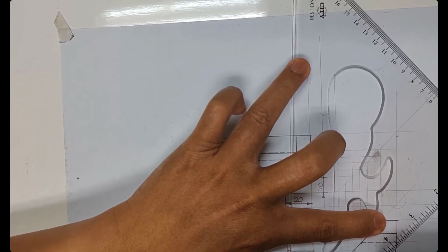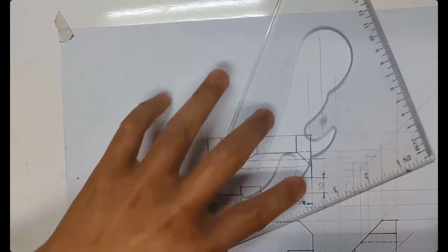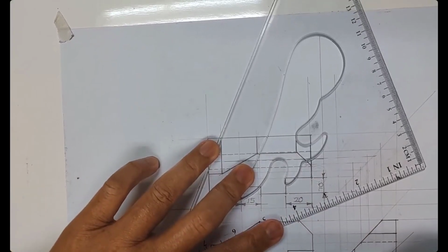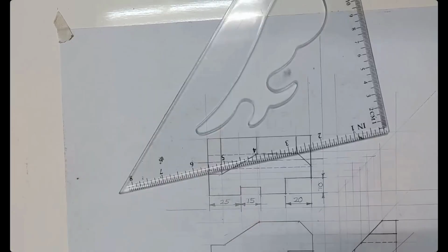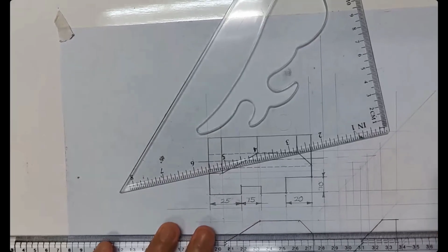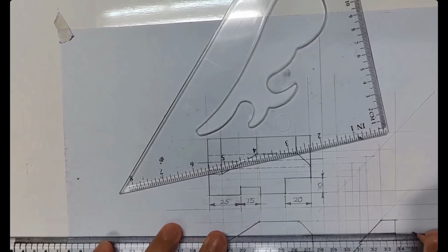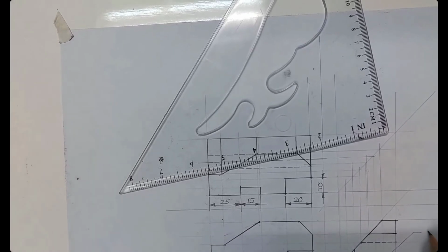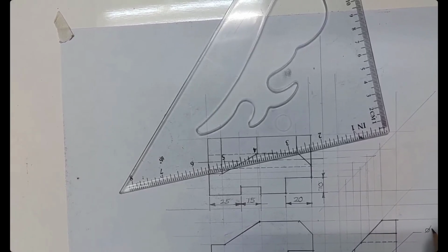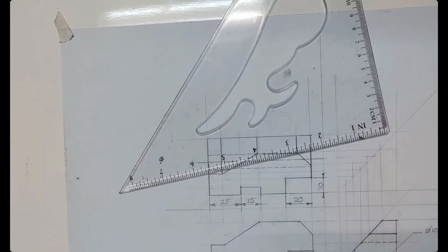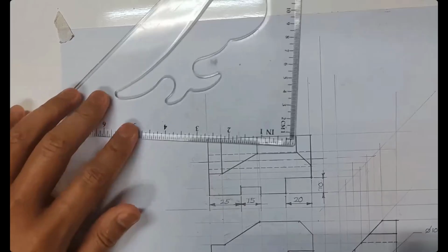Instead of using this line, this is a leader. I can make the arrow, but it's passing through the center point of the circle, so I make an arrow here like this. I can make an arrow here, something like that. And this one, we have an arm. Arm must be to the side and always horizontal. So you can write this one diameter 10. Make sure you write it properly. You can read that. I'm not too far away. It's about this position. All right, okay.